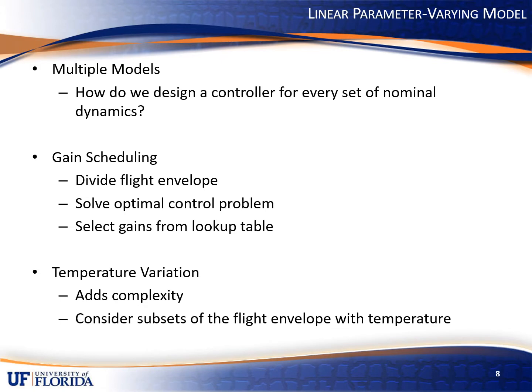But this type of technique does not really scale well to this type of problem for hypersonic vehicles, because the added complexity here is that in addition to dividing up the flight envelope, each segment of the flight envelope also must account for significant temperature variation within each one. In doing so, you end up with a very large number of segments to design optimal controllers for, and similarly, you wind up with a very large lookup table that you must use to store your optimal control policies.